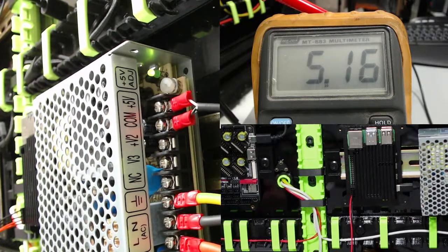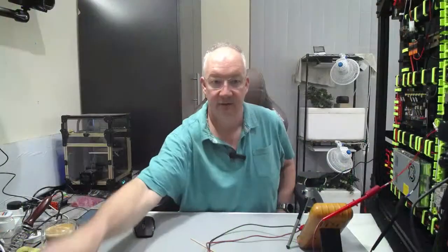Now my Raspberry Pi has got at least a decent voltage, and I think that's something that should be documented for people building up their printers that are going to push their printer a little bit harder. That, hey, you know what, extra bit of voltage on the Raspberry Pi at about 5.15 is a good idea. Okay, that being said and done,